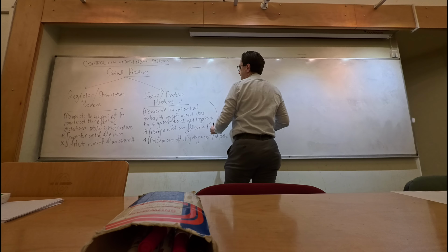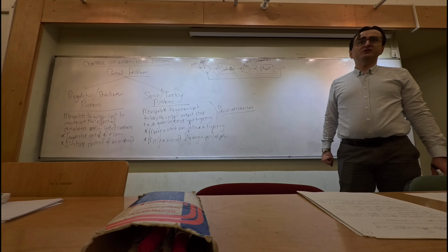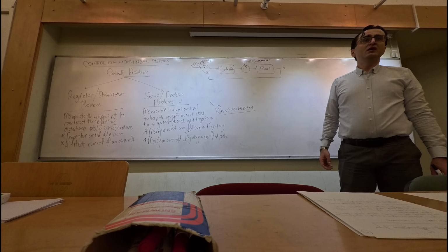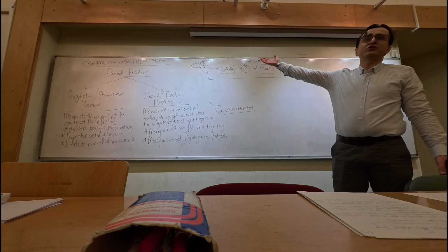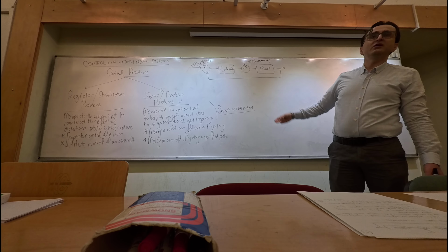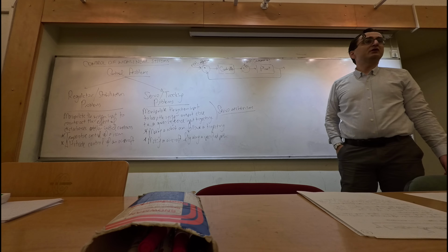And actually, I can say that sometimes the distinction between these two systems is not really that clear cut. Sometimes this distinction is blurred to some extent, because what happens when the reference is changing and the disturbance is also a non-negligible signal? In that case, we have a servo problem where the disturbances would be important, so the controller should act in both the regulator and the servo manner.